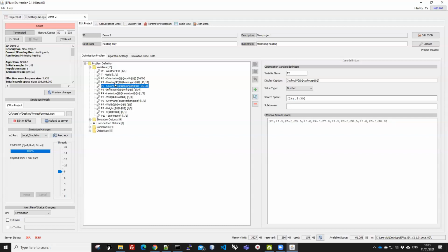Now, just to think about the situation, this is a single room in London, and it needs heating and cooling. Those are the 3 design parameters you can use. Now, without optimization, can you think what your best solution should be if you're looking to minimize the heating consumption? It should be south, lowest heating set point and highest cooling set point, right? Yes, almost completely right. So does everybody agree with Peter?